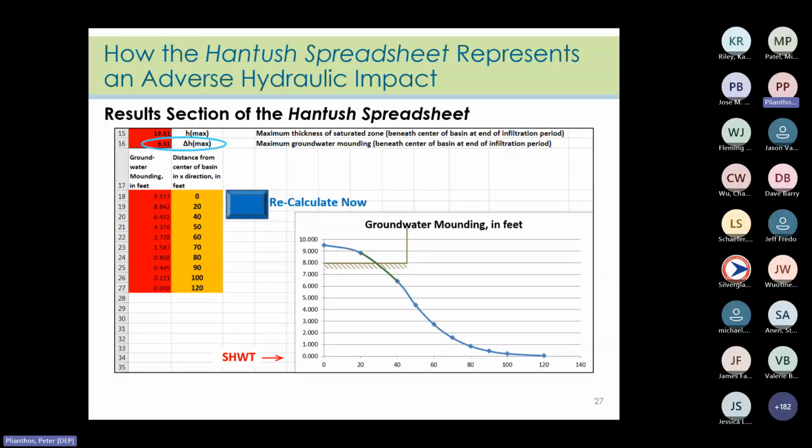Although we don't know the exact rate to which the rate will slow, even if it is slowed by 1/2, we're going to check the mounding for a value of T that is within the maximum allowable time period. Sometimes we call this stretching the infiltration period.